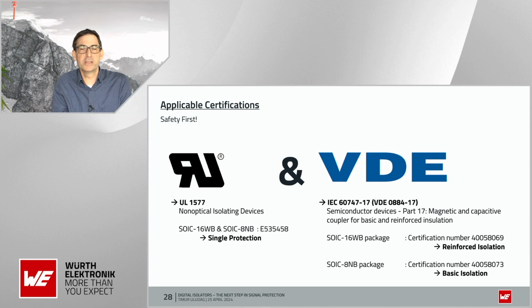And there you can see this is a standard that is specialized for magnetic and capacitive couplers, for basic and reinforced isolation. For the SOIC 16 wide body, we got the reinforced isolation certified. And for the SOIC 8 narrow body, we have got the basic isolation certified. The certification was done by the VDE in Frankfurt, Germany.